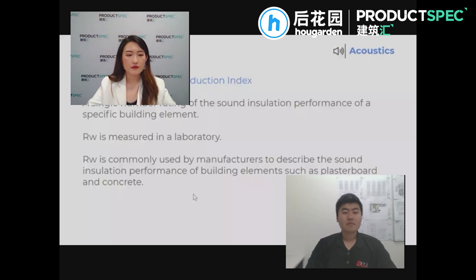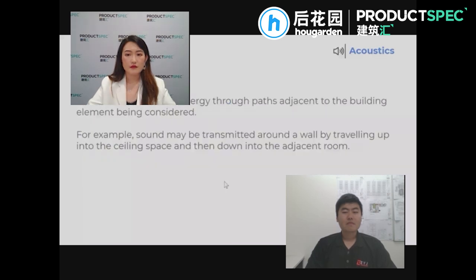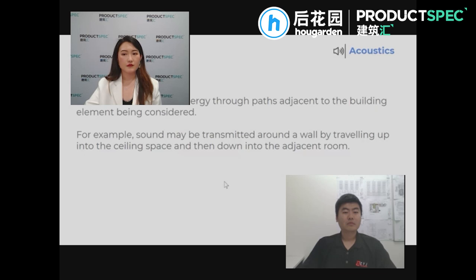One of the most important considerations when you're designing an acoustic walling system is flanking transmission. Flanking transmission is the ability of noise around the end of the wall to travel around and into the next tenancy. So we have specifications and requirements to achieve elimination of flanking noise.